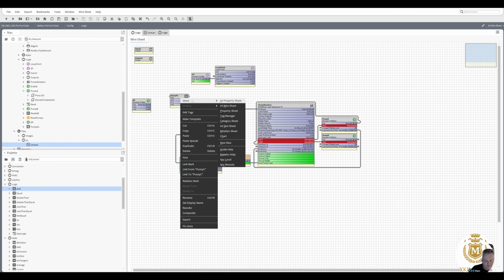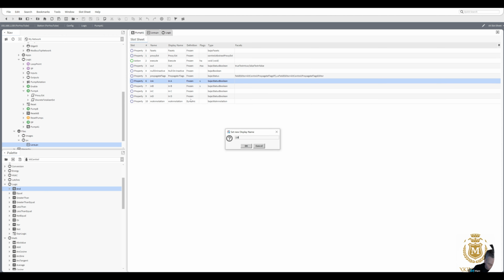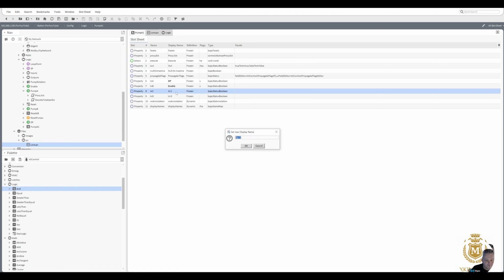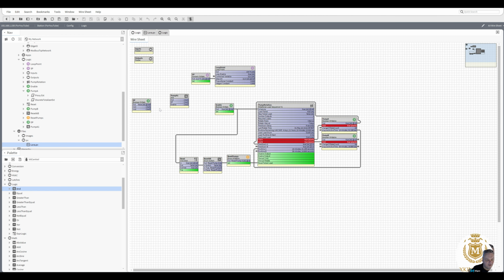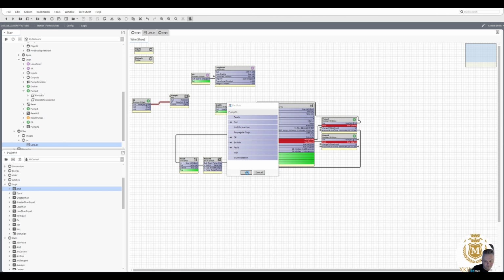And let's just tidy this up in the respect we put DP there, and we put enable there, and then we can even do the fault in case we get a fault signal from that pump. Fault in there, and then I would put my DP into there. Let's expand this because I've got the fault in there now.